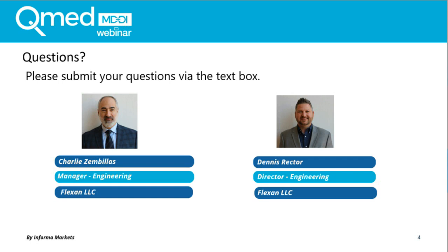We'll move on to another question here for you. Our next question asks, I've heard of platinum cured silicone. Is this about adding a platinum-based additive during milling? No. So unlike peroxide cure, where there's organic peroxide that's added to the silicone while you're milling, with platinum cured silicone, it's put in by the silicone manufacturers. It's a very trace amount of platinum, which just is the cure mechanism when heat is added. All right, thank you, Dennis.